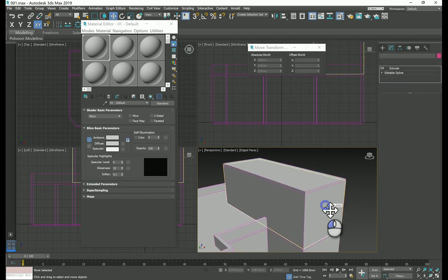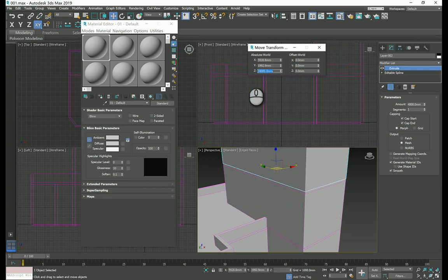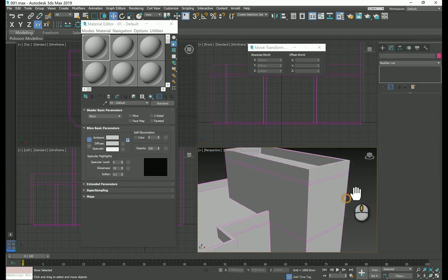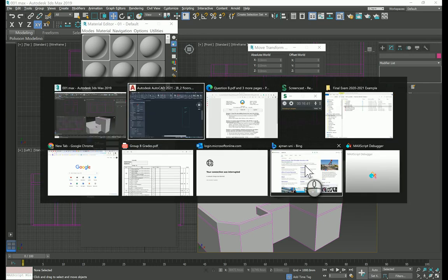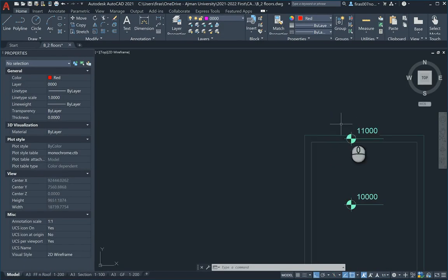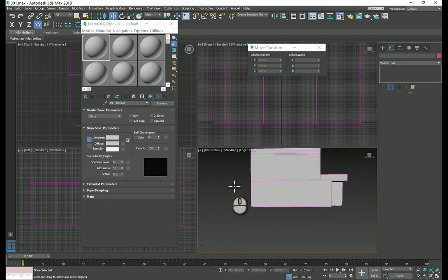And then I'm just going to hit Control V. I'm copying this again, and I'm going to push it to 10,000 like this, and make sure that this is just 1,000, making the parapet like that. So one piece, two pieces, three pieces, if that makes any sense. Optionally we can create it one way or the other, as long as the walls and the parapet are the same thickness and the same material. Anyway, that's 11. Beautiful. So I think that's it with the mass itself.